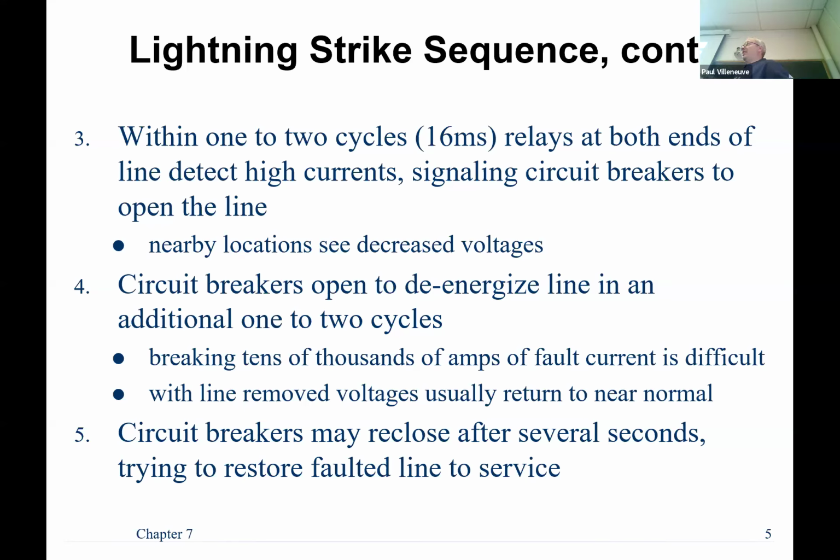So one of the ways that you detect that the fault is still there: open the breakers, clear the fault, and you hope. If the fault is still there, you don't know until you close the system back in. And then if fault current still flows, then you open the breakers again. Sometimes you can do another attempt. I don't know why this is the term, but they call it a reclose shot. In industry, they call it shot 0, shot 1, shot 2.